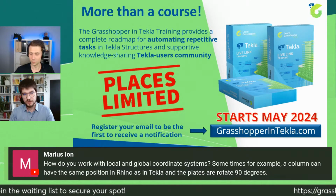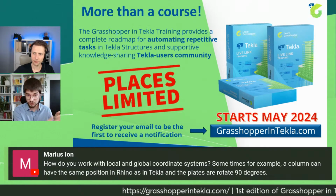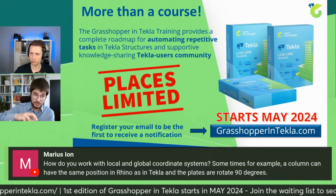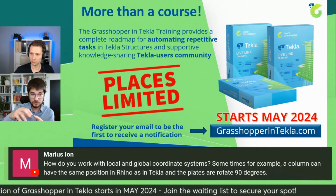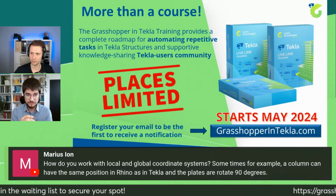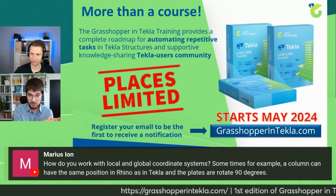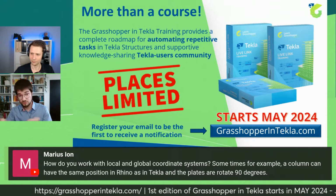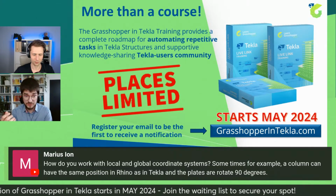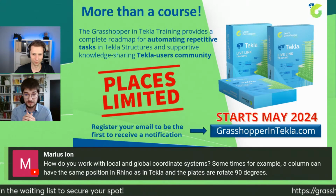Okay, so each view has two different coordinate systems. The one which was initially created, the view coordinate system, and the second one is the display coordinate system, which takes into account your rotations of the views. So when you are asking the view about its properties, you are getting two different coordinate systems, and usually you are working on the display ones. So you are getting the model object in the current model coordinate system, and then you are projecting it, orienting it to the view specific one, because each view has a slightly different coordinate system. It can be attached at a different origin, or it can have completely different X and Y axes.